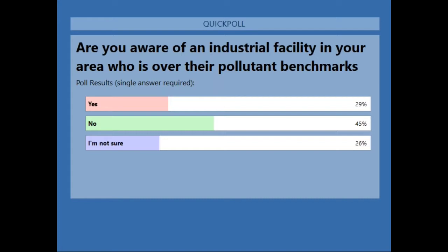Last thing here, waiting to take action could cost you money, and long term it could cost you using the proper system, because you might be dictated to as far as what system you have to use. So essentially, don't overdo it, don't pay more than you should, and don't underdo it. Don't use a catch basin insert when you need an actual filtration system. Not that they don't work, they're excellent. And one last thing I should note is, because you put in a treatment system doesn't mean you don't have to do typical maintenance either. You have to keep that up as well, housekeeping that is.